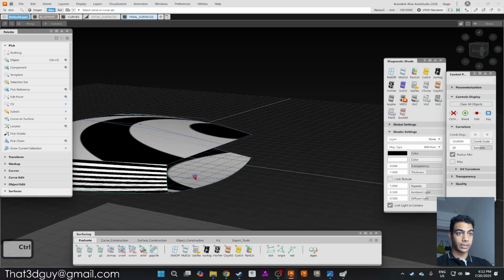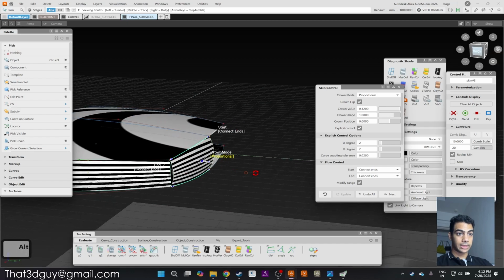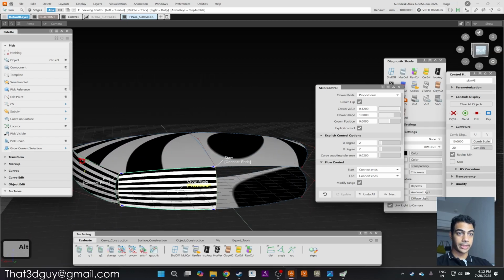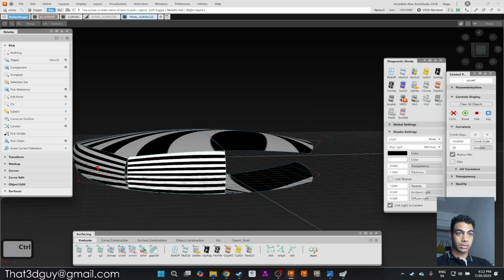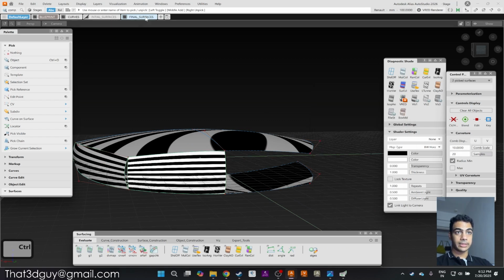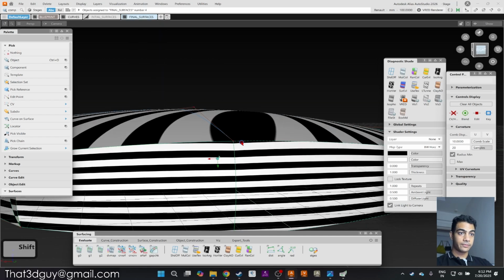And let's try to do a skin here as well on this side. So skinning, and looks okay to me here. And now let's mirror these as well into final surfaces and assign. And now if you see, I can already see there's a breakage here.